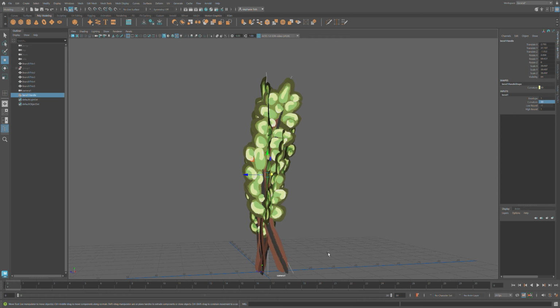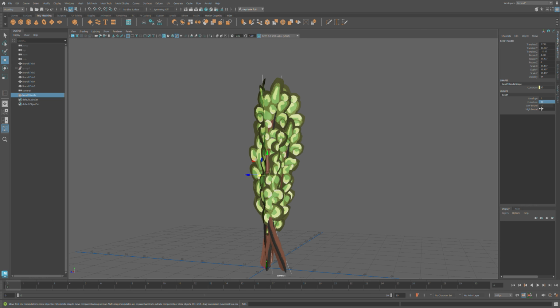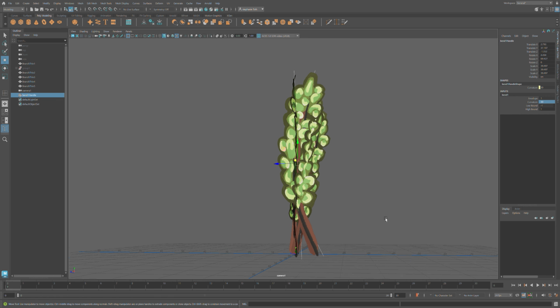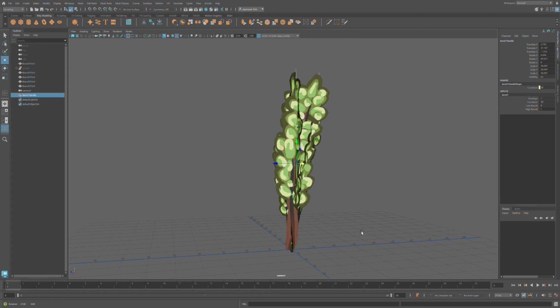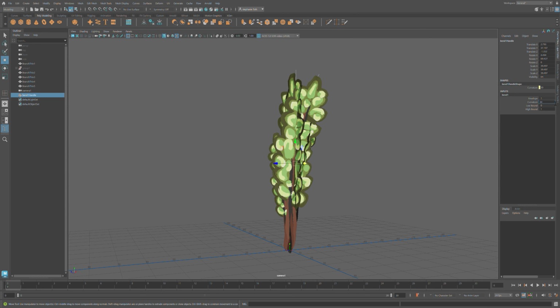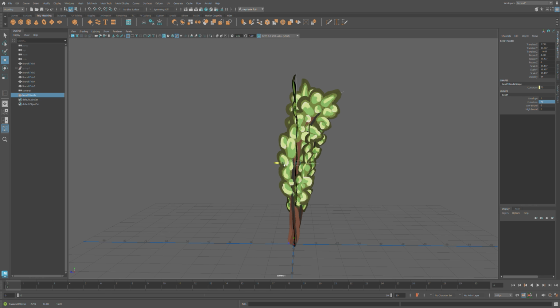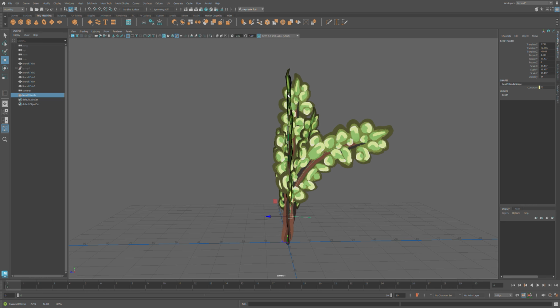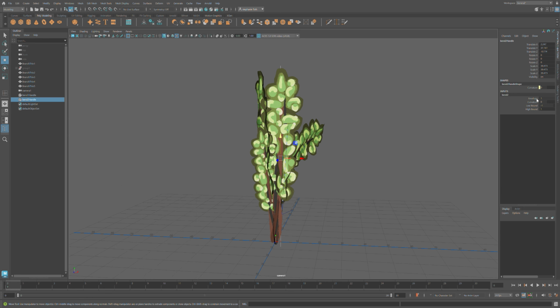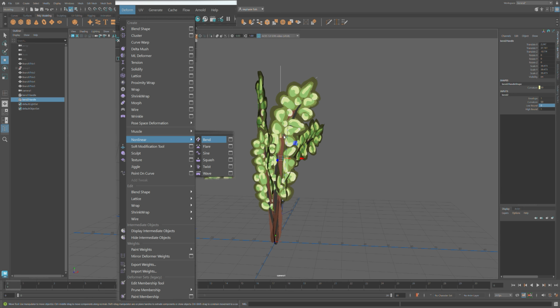So we have bend of our mesh, and we can change the low bound because I want this bottom part to stay sort of at the center there. We can just click and drag that to 0 so that it stays there. And then let's just keep pushing the curvature. I'm just going to move this bend handle down a bit so that we get that stretch. And then we can just do the same thing again. Let me add another bend.